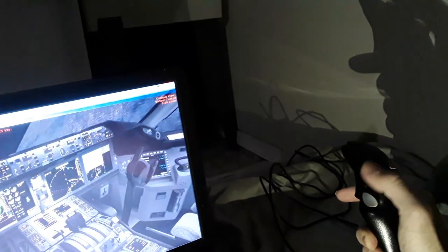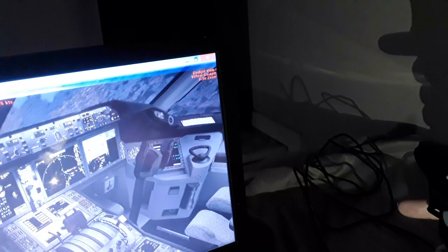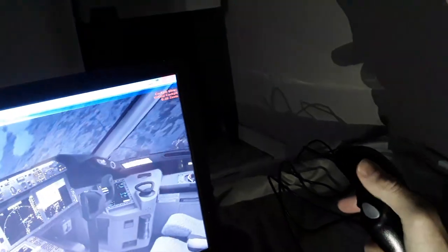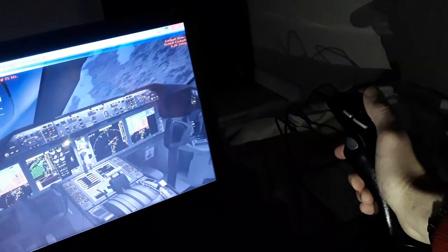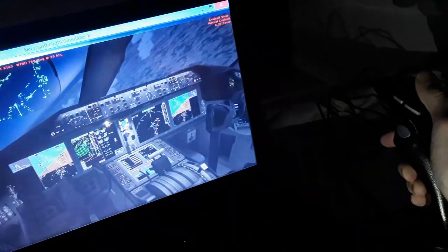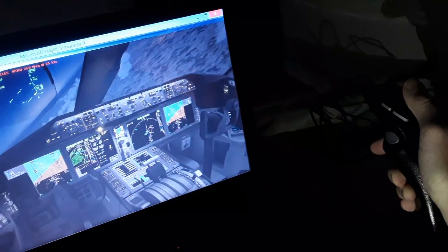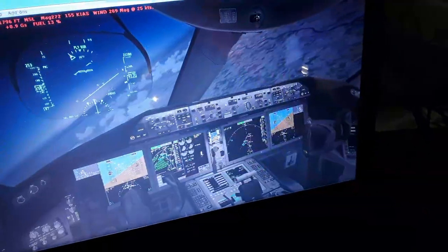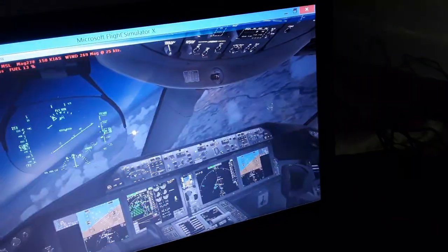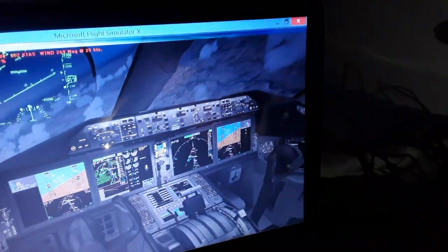We need to align now with the flight plan and go back to the airport for landing. We have a few more minutes, so make a more rapid turn over here, many degrees faster. Use a bit of right rudder, as you can see, and align again with the flight plan.